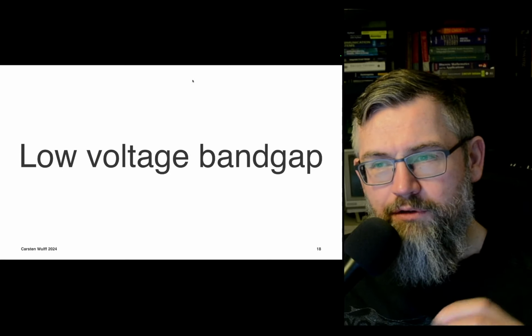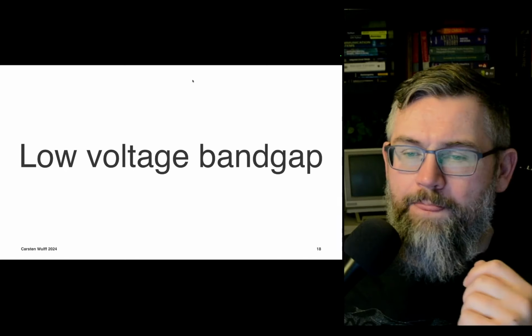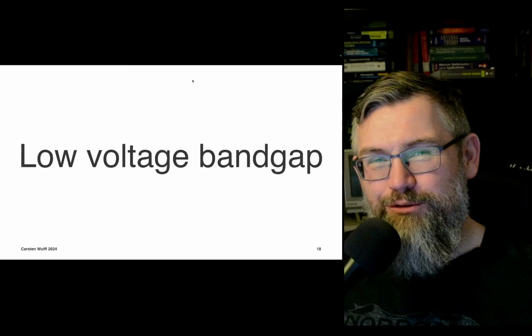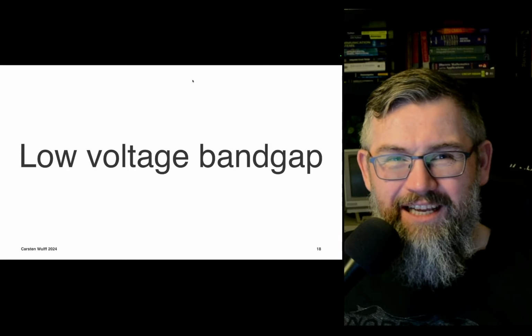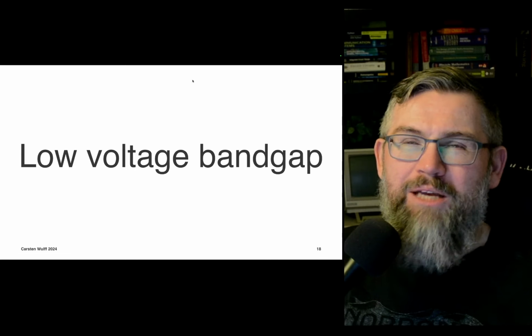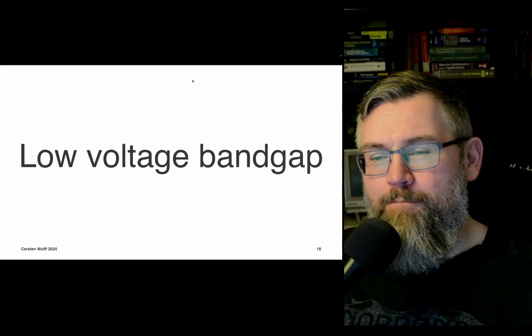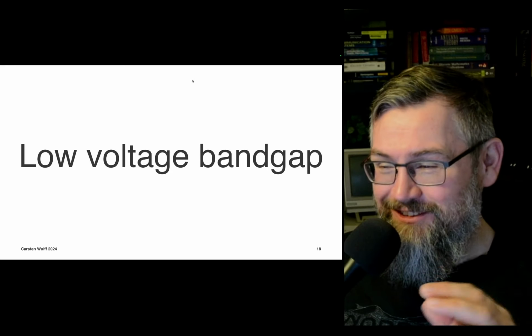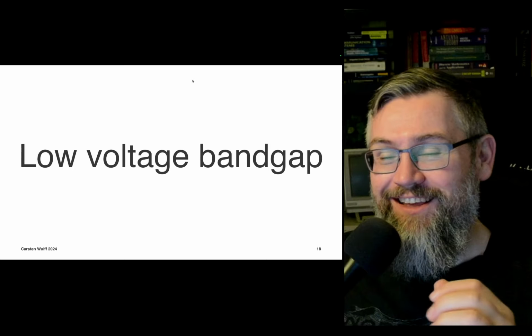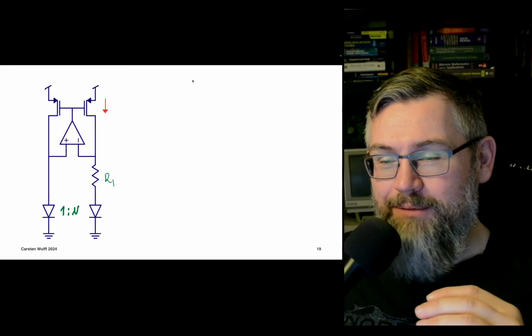But in modern technologies, if you don't have IO voltages, you only have the core voltage, like 0.8 volts, then it starts to become tricky. But usually you have an IO voltage. Usually you have 1.8 volts, at least in most, maybe older technologies, 22 nanometer and up. Probably lower down also, you have 1.8 volts. So you might not need a low voltage bandgap, but if you have to make a bandgap at around a volt or something like that, then the low power voltage bandgap is the way to go.